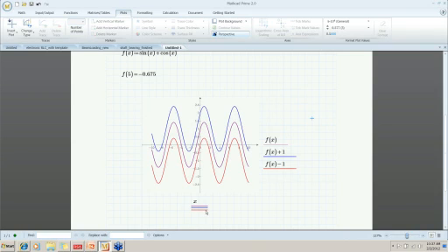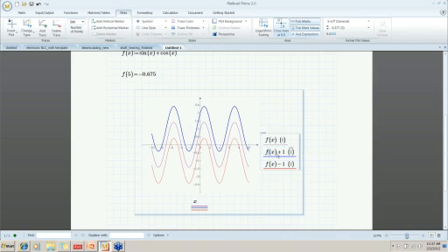You can see that. Now, if I wanted to add a marker to this nominal trace, f of x, we'd go up here and, well, we could change the thickness of the line just by selecting a new thickness. And now you can see here it's thicker. And then we could do that for the other ones as well. So it's incredibly easy to make these changes.